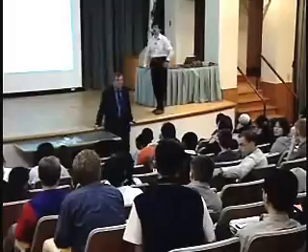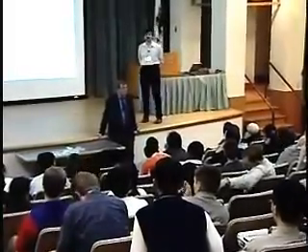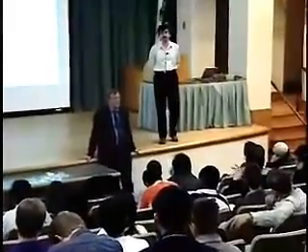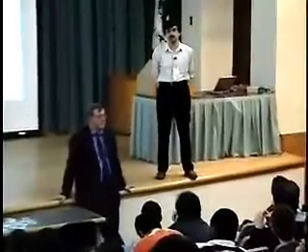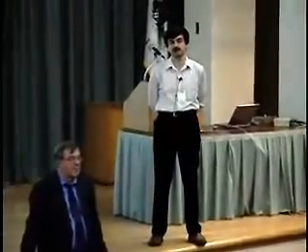Well, what happens is you're looking at a non-equilibrium case here. You're looking at how the temperature of a protein changes. I mean, that goes from 300K to 200K. After that, it will stay at 200K. You can run the simulation as long as you want, because if your integrator and force field and everything are right, its temperature will stay at 200.